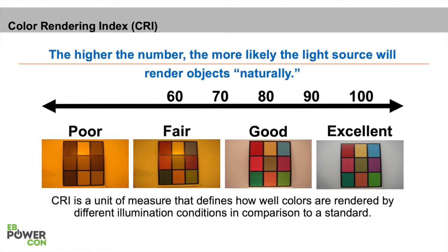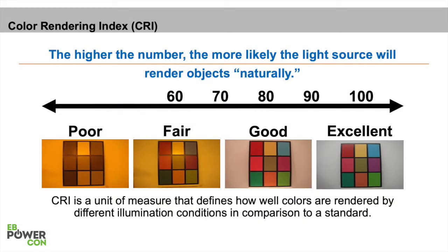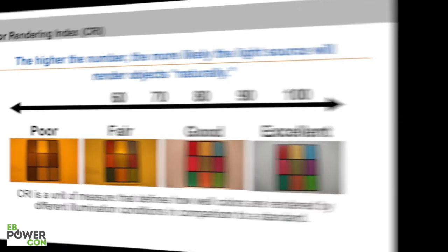If you have that high pressure sodium, you may say it's a gray, but really it could be a blue because the color rendering index is just not there. And I'll explain how that works. When you look at a color rendering index of 70 or above, we typically say that is very good. You'll be able to see what the color is.